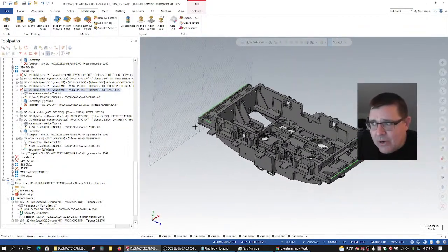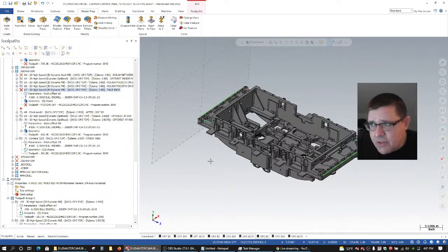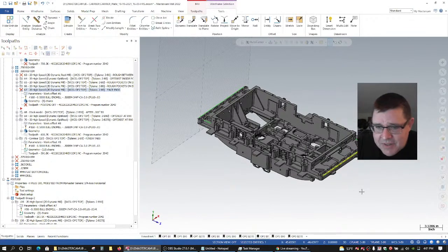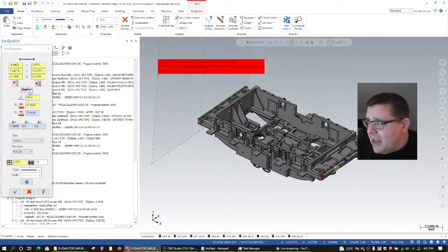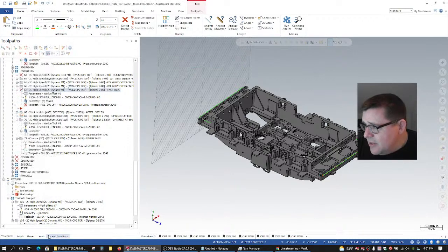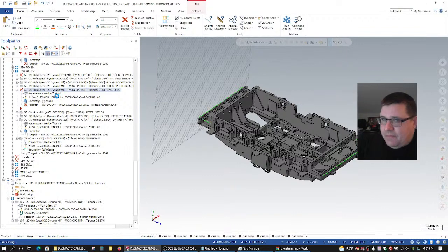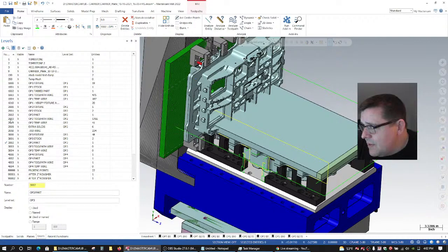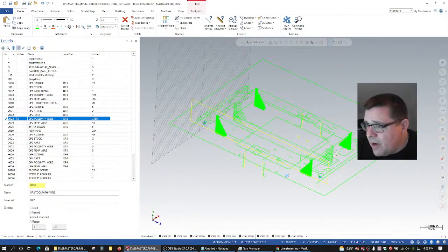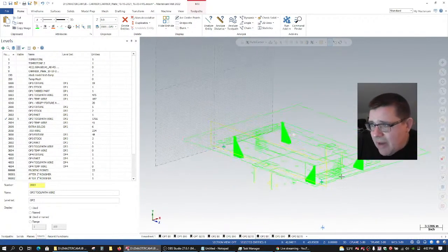the equation. So how do I tell if there was other stuff on that level? Well, I'm going to select that. I'm going to go and choose Analyze Entity, and it's on level 2003. So now I'm going to turn off Only Display Associative Geometry. I'm going to go back to my levels, find level 2003, and turn that off.